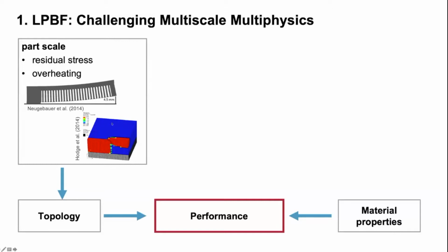The blue region here is powder, unmelted material, and the red region is melted or solidified material. Of course, in the powder we have voids, so the powder isolates. The heat cannot escape as well as when we melt over the solidified regions. So heat gets trapped, and then we can have this undesired enlargement of the melt pool.